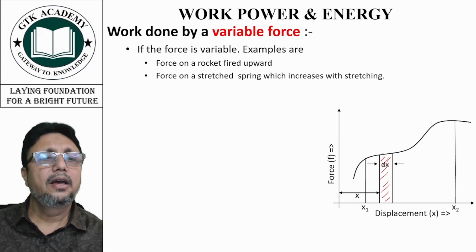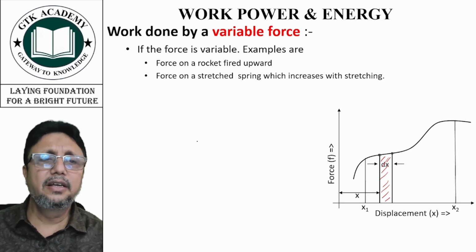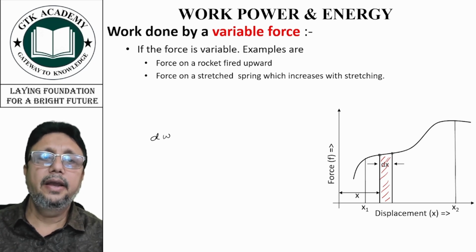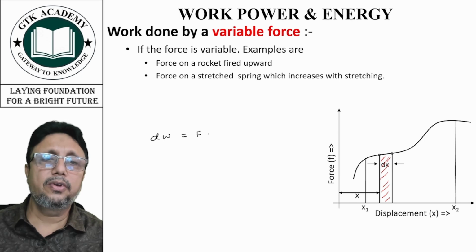Now here, although the force is also varying very slightly, if the strip is very small, force can be considered constant in this small strip. So the small work done dW in this strip will be equal to the force in this strip, which we are taking constant, into the small displacement, which is dx.